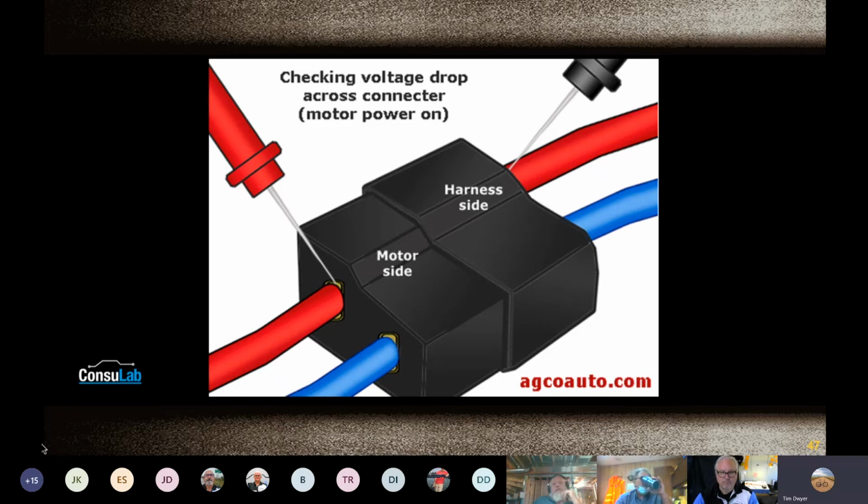And it could be any variety of 12 volts. It could be 8 or 9 or whatever, but a 12-volt would almost indicate that wire, that harness inside there, that plug-in is burned or something. Correct? Yep. And what I was telling you yesterday, man, I did it for so many years, and I would have probably just unplugged that thing first and started testing.